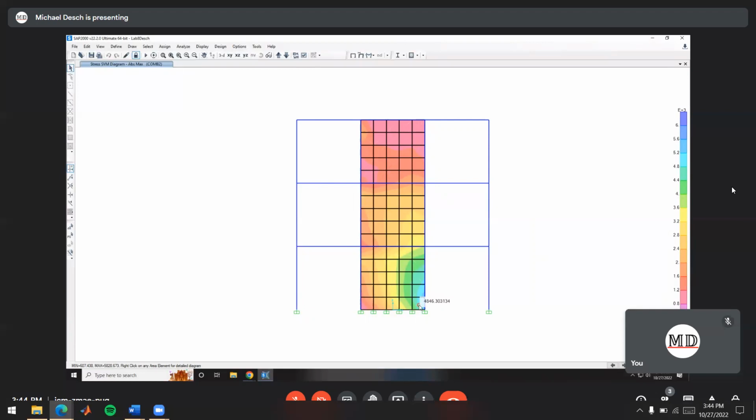So you'll see these in a couple places around the world, but they're mostly highly seismically active areas. There's a lot of other lateral force resisting systems that are much better suited than needing to put in a whole piece of plate steel for a whole bay. They're a little easier than that in most applications, but this is a good one because it just keeps everything in steel, and we don't have to worry about adding in concrete modeling for this class. I just did it for the simplicity of keeping everything in steel, because composite stuff is a little harder to model.